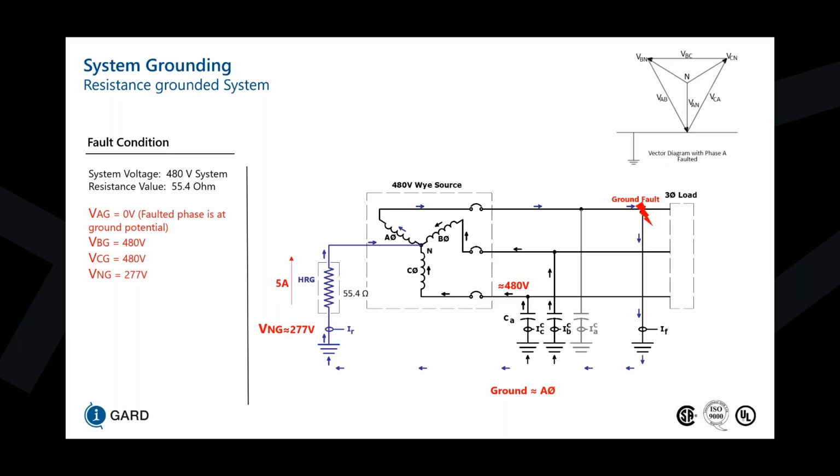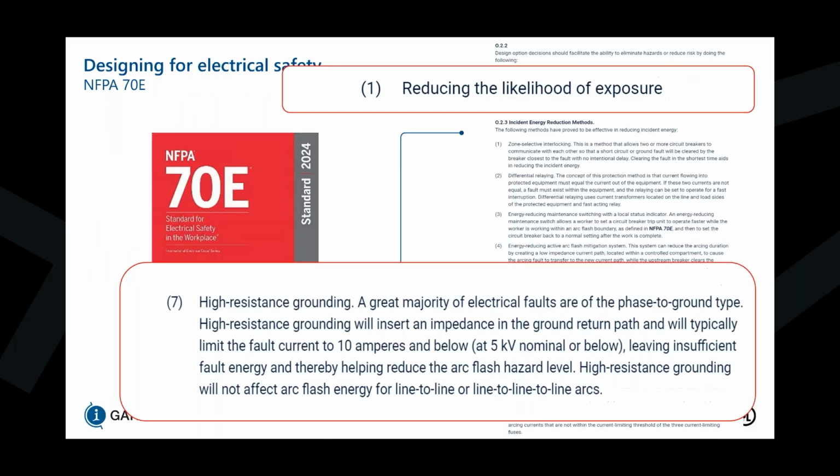So we have basically shown you what happens during a ground fault scenario and how we are able to achieve process continuity in the event of the first phase to ground fault. So we're not tripping the faulted feeder. All the unfaulted feeders are still operating based on the voltage present for the system, and this is how we're achieving that process continuity.